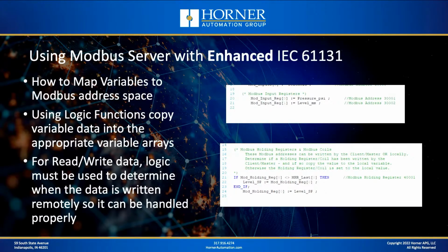Now, an important note here, and that is on the bottom right, I'm showing you that I didn't just use a simple assignment function for moving variable data into holding registers. The reason I didn't is because if you have data you want assigned as a holding register, and you're truly going to allow that to be a read-write type scenario where the data could be written locally, maybe it's a set point for the PID loop or something, or it could be written remotely, maybe making an adjustment over a SCADA package of that same data, then you need to have some logic that detects whether or not that variable was changed remotely or not.